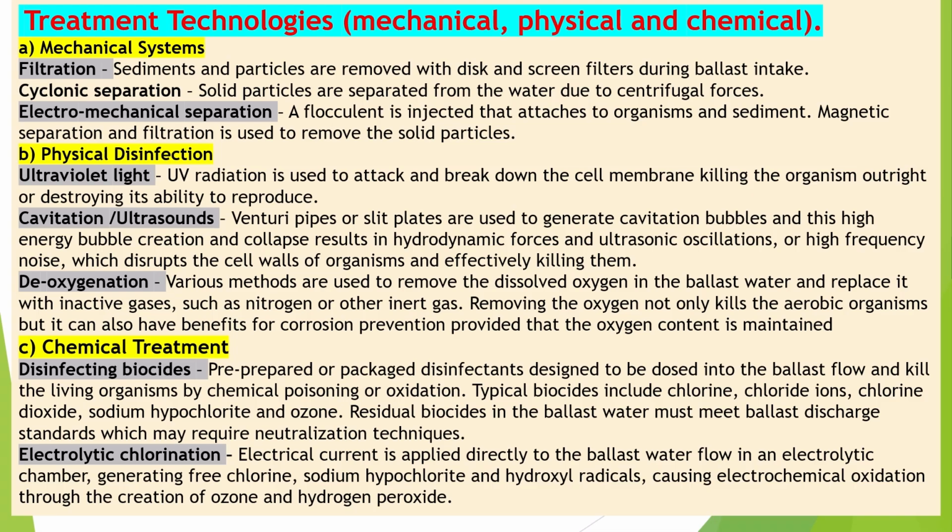C. Chemical treatment. Disinfecting biocides, pre-prepared or packaged disinfectants designed to be dosed into the ballast flow, kill the living organisms by chemical poisoning or oxidation. Typical biocides include chlorine, chloride ions, chlorine dioxide, sodium hypochlorite, and ozone. Residual biocides in the ballast water must meet ballast discharge standards, which may require neutralization techniques.